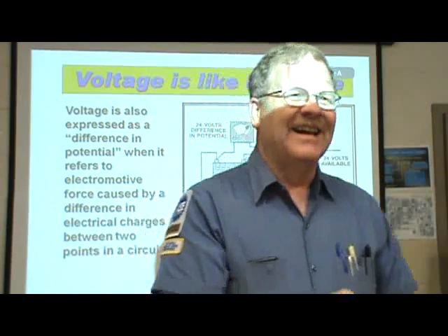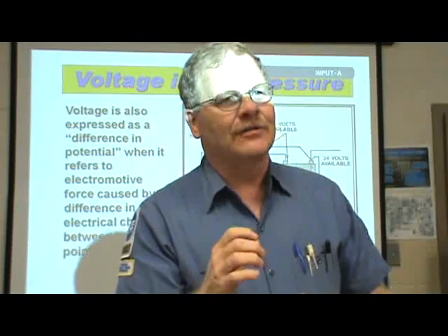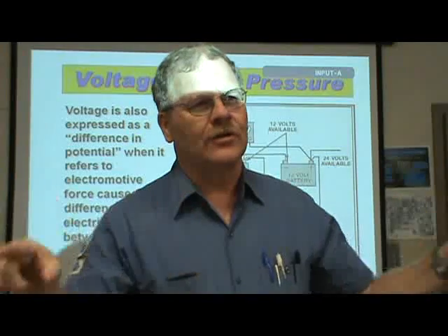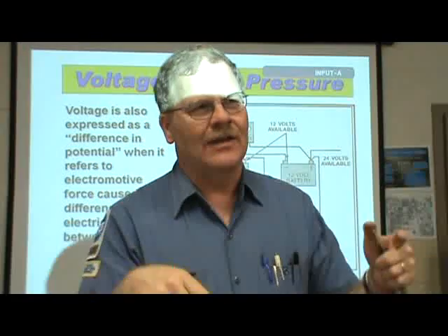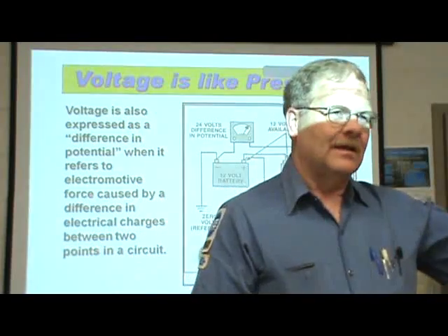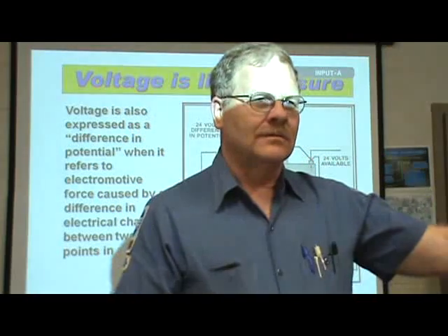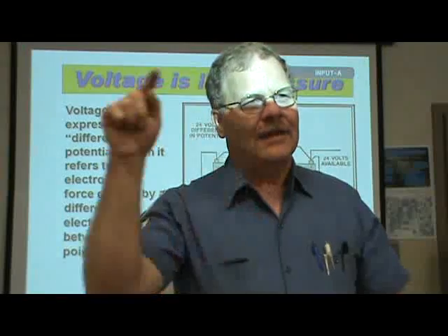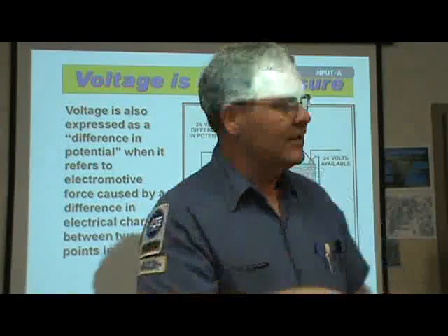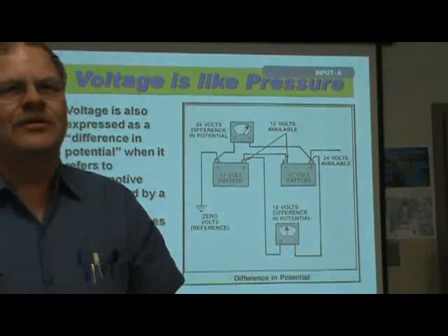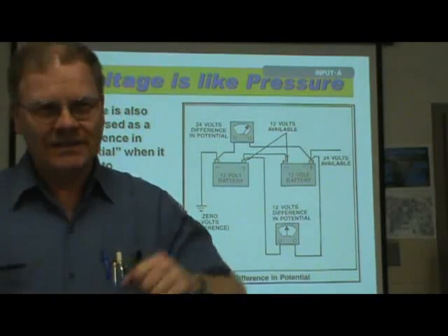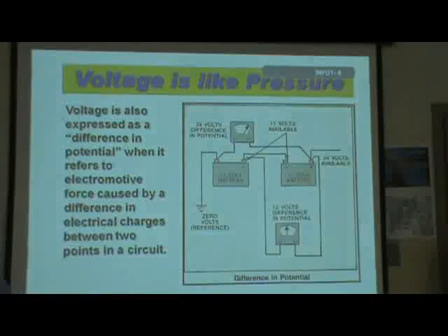Go for it, keep going. And then I'm going to hook the positive to his positive terminal. And then I'm going to hook the other two cables together. So I've got one going from the negative battery terminal on the vehicle to the positive terminal on his battery. I've hooked the batteries in series, you see. And so that puts 24 volts in the starter. And boy, does it ever spin that thing fast. Fire it right up. Scares the stew out of somebody when they see you do all that.